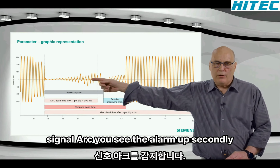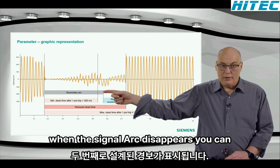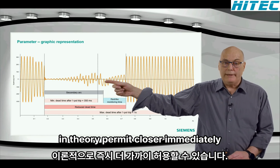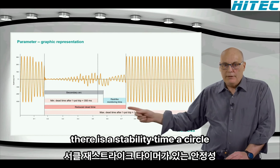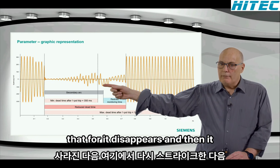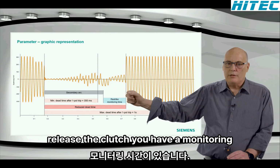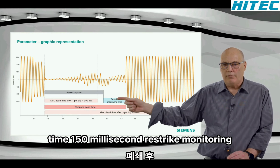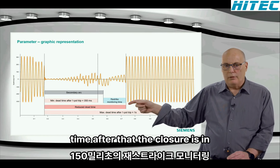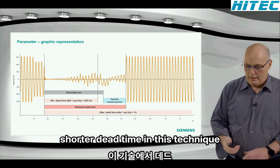When we detect the secondary arc, you can see the alarm up, secondary arc detected. When the secondary arc disappears, you can, in theory, permit closure immediately. There is a stability time, a so-called restrike timer, just to put it. Could be that it disappears and then it restrikes here, then you don't want to release the closure. So you have a monitoring time, 150 millisecond restrike monitoring time. After that, the closure is then released. You can have a much shorter dead time in this technique.